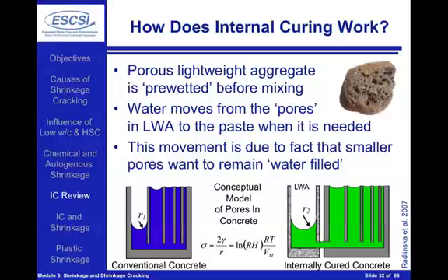Before the concrete sets, there's really not a pressure developing inside of the paste. There's really not a need for water to come out of the lightweight aggregate because the system can keep collapsing upon itself, and we're not really creating a lot of vapor-filled spaces or under-pressure that needs to be dealt with. However, after setting, once we've locked in the microstructure of our concrete, now all of a sudden we can supply water that's only going to help reduce shrinkage and increase hydration. This is like a trigger that says, okay, let's start taking water out of the lightweight aggregate and start internally curing our concrete.